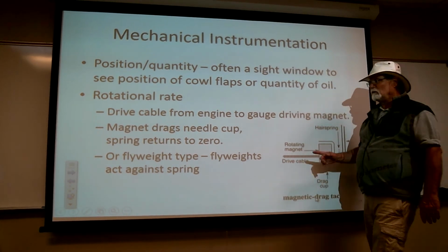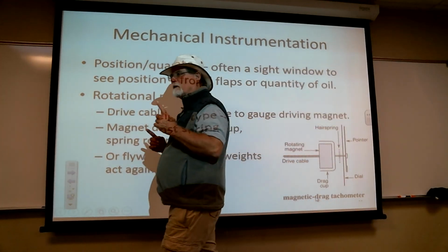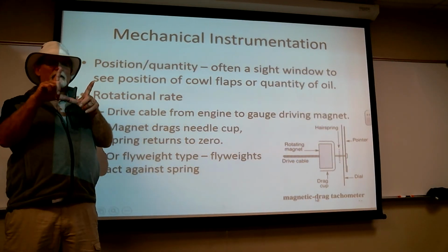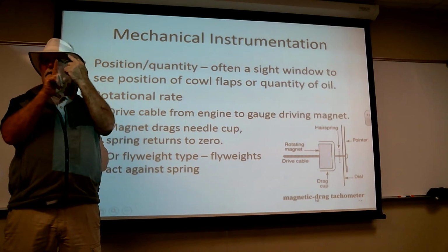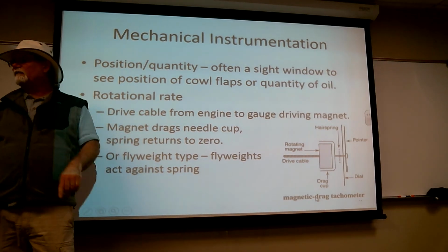Another type is they actually have flyweights going out, and as the flyweights go out, they push a spring up, and as that spring goes up, it pushes a little sector gear that then drives the needle.